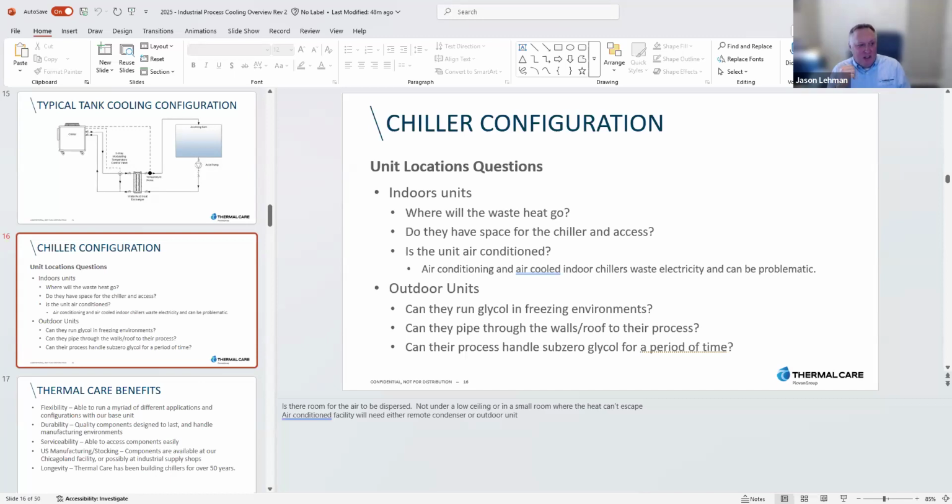Most importantly, it cools with air. The air has to go somewhere. It's heated up about 30 degrees. So if their plant is at 85 degrees in the summer, it's going to heat it up to 115, and it's going to put a heat load in their system that could be comparable to a couple of home furnaces or even more if they've got a bunch of these. So it can really heat up a small space or even a large space over time.